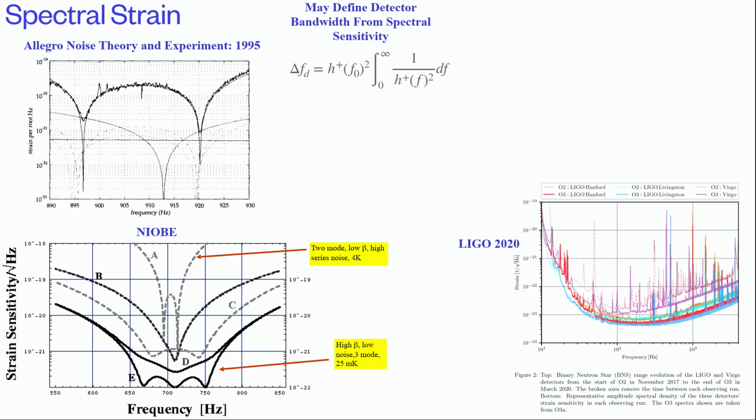No matter what my bandwidth is, if I press the button for per root hertz, I'll get the same thing. If I press the button for volts, I won't, right? If I'm measuring some noise, then you have this resolution bandwidth that goes between the two, a resolution bandwidth which you must know if you want to convert between the two, but the spectrum analyzer does it for you, okay?